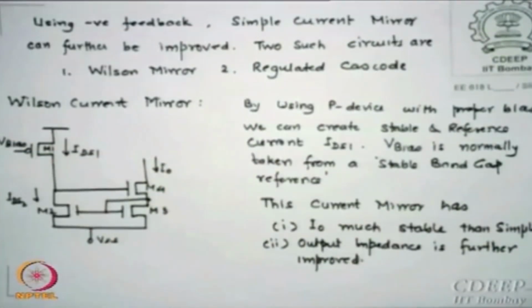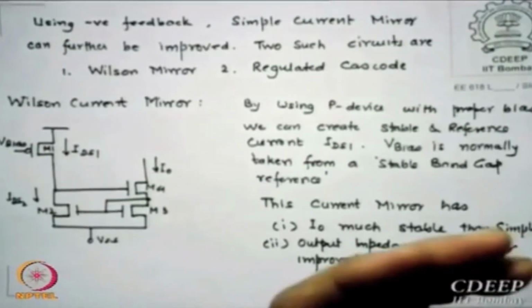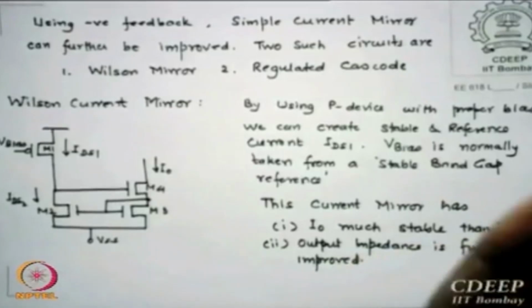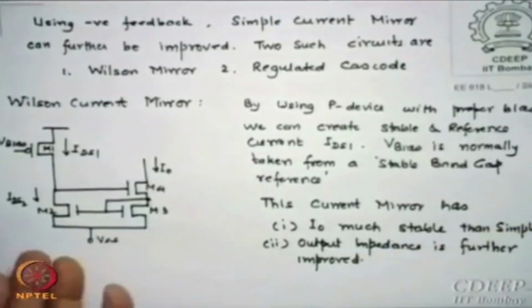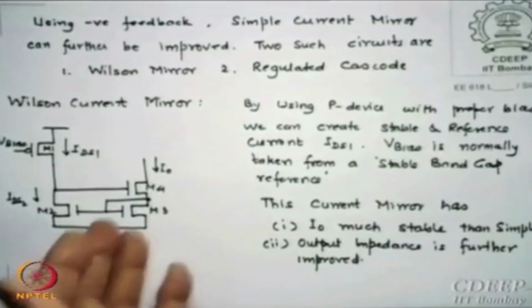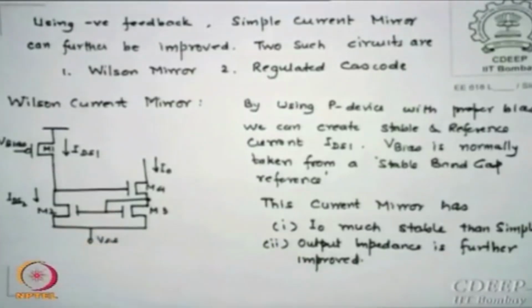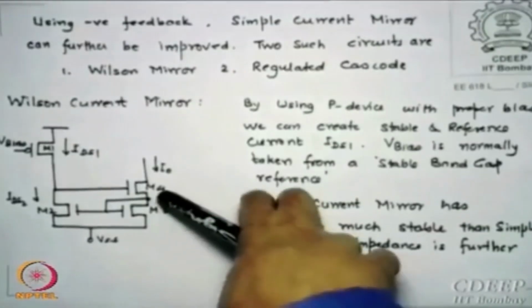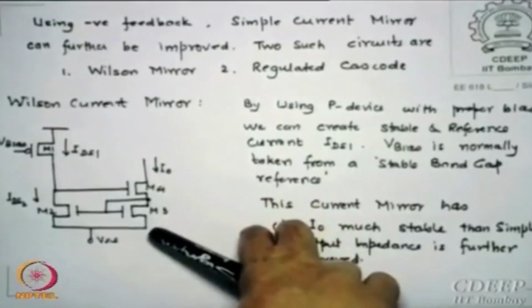So this is what essentially negative feedback does. Is that clear? And since negative feedback allows you to stabilize, which is the standard way of stabilizing anything, you can use a partially cascoded mirror using Wilson current mirrors, Wilson connections, and say that it will be much better than normal cascode sources. Is that clear to you? You did not get it. IDS1 is constant, but by force you are trying to change IDS2, which is coming from the mirror from the M3 side.